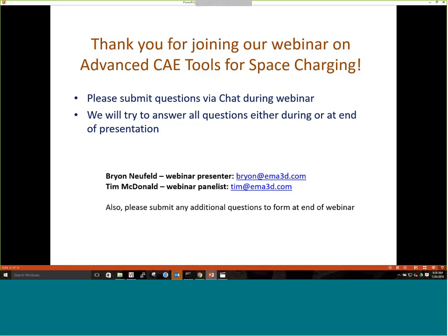Yeah, and like you say, Brian, I've had experience with this, taking the mechanical CAD files and combining several surfaces together to make it simpler, and then you get fewer mesh elements. And I think the computation time is like number of elements squared. So I have seen it be a problem, and I've been able to use Cadfix successfully to simplify that down.